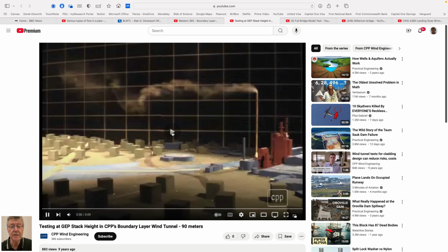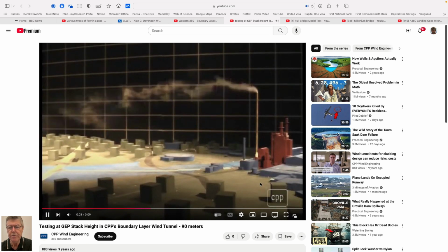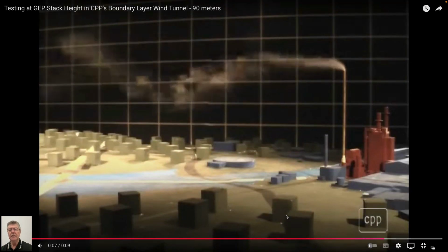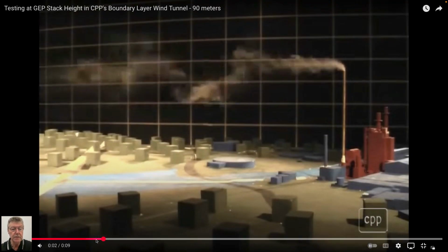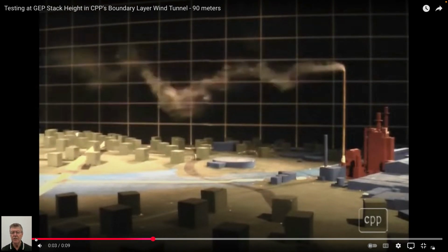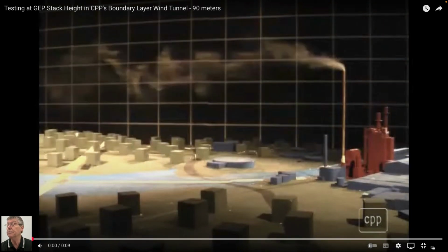Other kinds of things, environmental systems engineers will do a class on air pollution, and so diffusion and dispersion in the atmosphere is something that's important, and you can have lots of interesting models, very simple analytical models, to look at what the concentrations you'd see would be downstream.